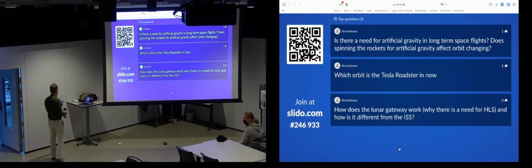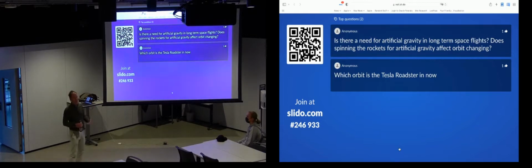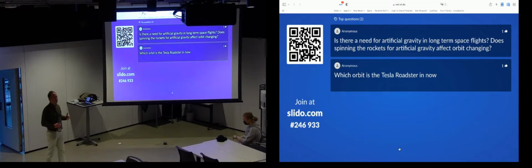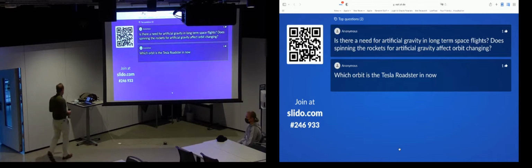The ISS orbit is a compromise between the launch capabilities of Space Shuttle and Soyuz. The inclination's too high, so Space Shuttle, to get meaningful payloads, had to lower orbit. Soyuz couldn't go any lower inclination at the time, and the like. The original American plan was obviously 28.5 degrees for inclination. Space Shuttle would have been several hundred kilometers higher for that. Okay?